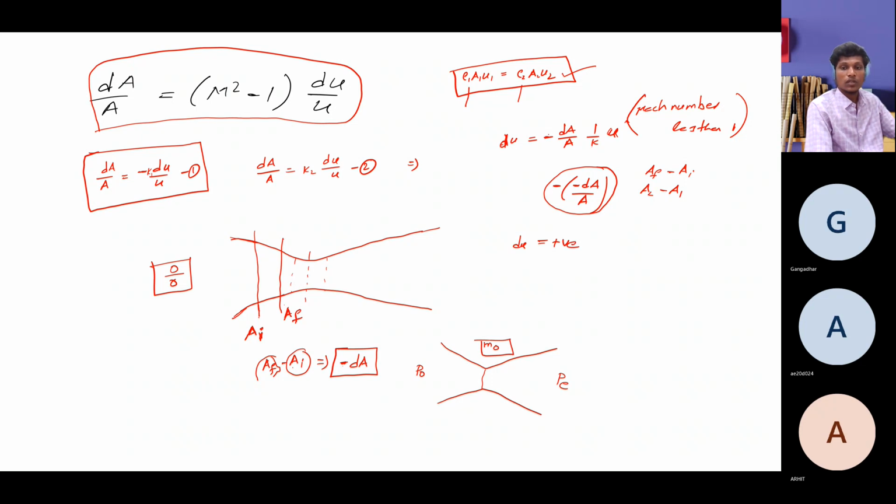It cannot reach or take more than some maximum mass flow rate because of the area constraint or the gas constraint. Velocity may increase, and at the same time density and velocity parameters differ, but this maximum mass flow rate will choke here. That condition is called the choked condition, in the sonic regime.